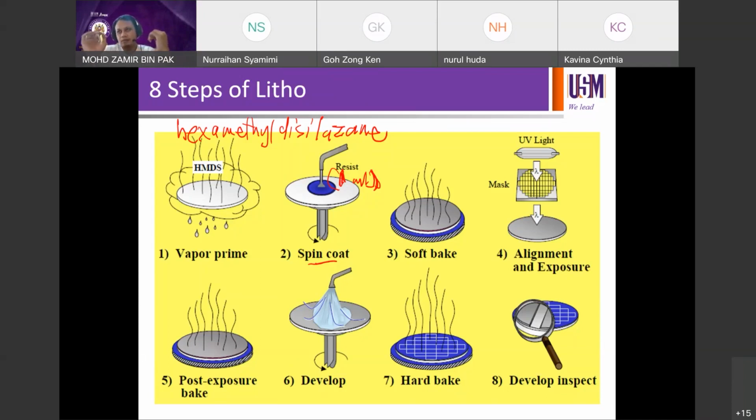Okay, so in the same industry, for example Infineon, we have layers which are classified as front end, and we also have layers which are classified as back end. Front end layers are all the oxide formation, and then all the STI, shallow trench isolation, implant, doping to make the source drain on the MOSFET, and gate oxide, gate. So those are considered front end layers.